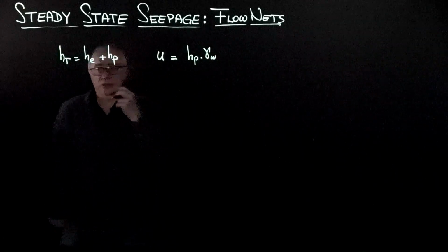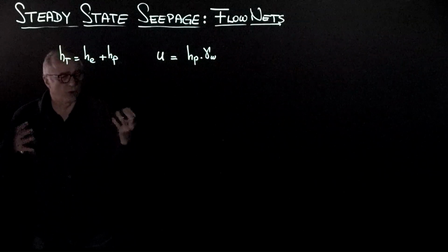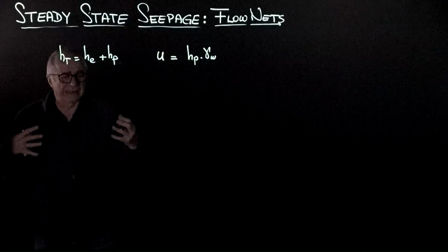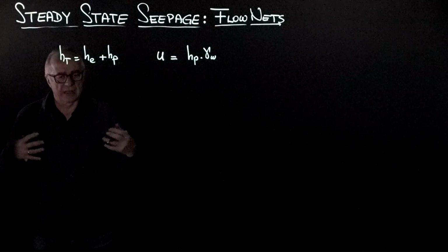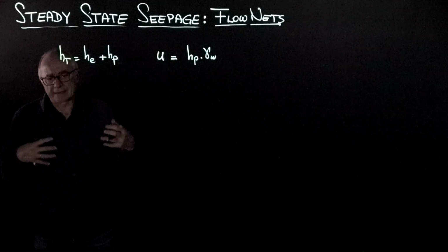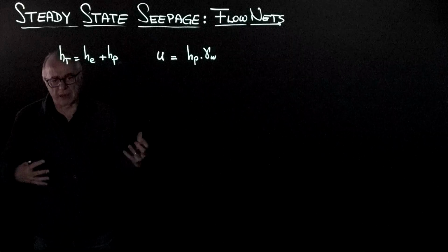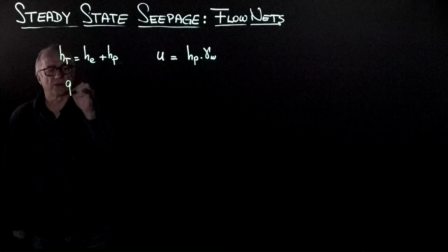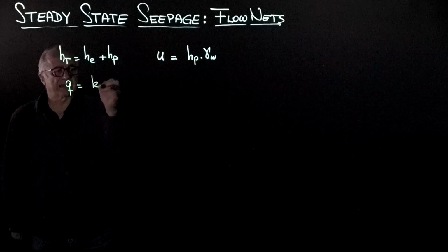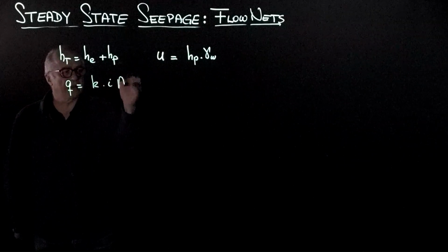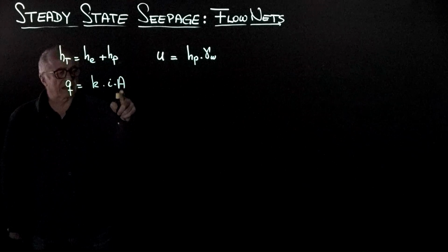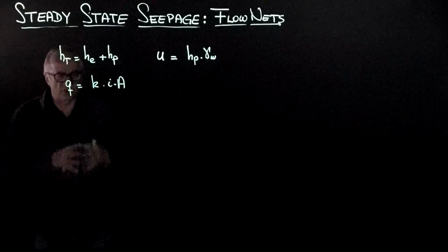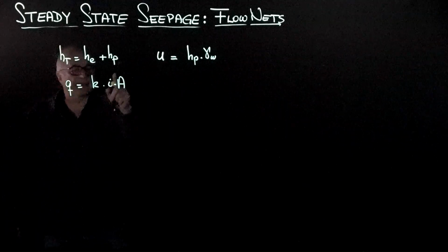The next equation that we use for most studies where we need to understand the amount of flow, the flow rate, and what will be the size of pumps, or at what rate we are going to lose water, is Darcy's equation, which tells us that Q is K I A, A being the apparent cross-sectional area, including the grains, I being the gradient.